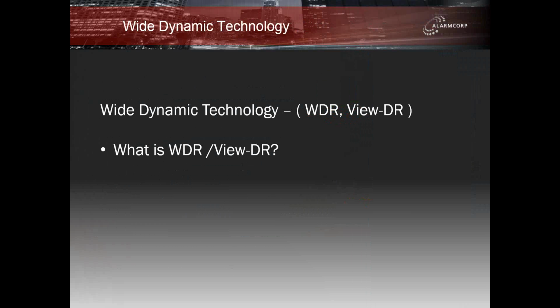WDR means a wide dynamic range of light level. Light changes at different times of the day, and depending on the actual camera location, this change in light can have a significant effect on the output that is displayed. Examples such as building foyers looking out towards a street, or car park entrances change with vehicles entering in the morning or in the evening with their headlights. In the case of a car park, the concentrated flare that the camera is exposed to from the headlights is a good example of where a WDR camera is required, especially if the number plate details are a priority.